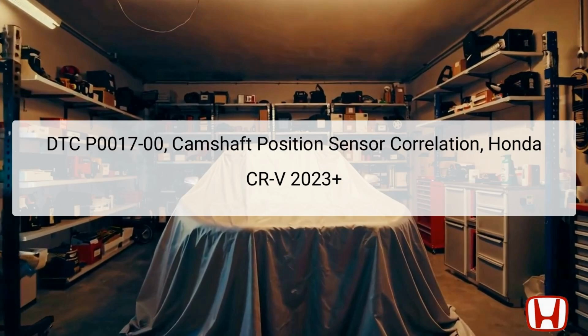A diagnostic trouble code, DTC P0017, indicates a correlation issue between the Camshaft Position Sensor B and the Crankshaft Position Sensor. This correlation is crucial for optimal engine timing and performance. The CMP Sensor B measures the position of the exhaust camshaft, while the CKP sensor monitors the crankshaft's position and rotational speed. Both sensors work in conjunction to ensure the engine operates efficiently.